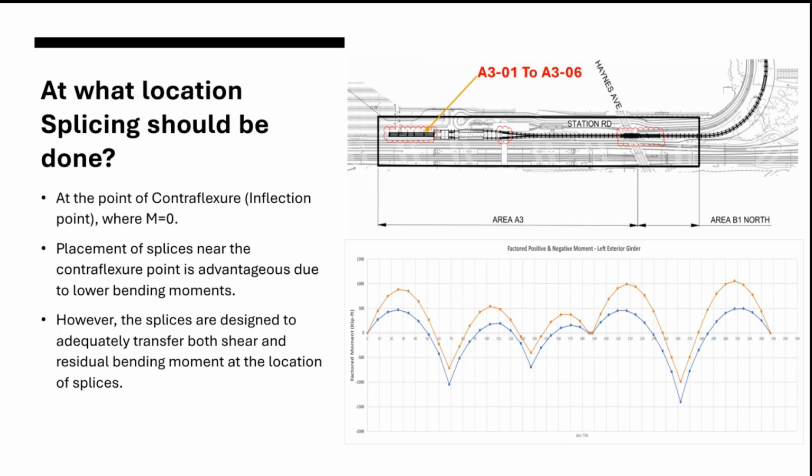If it's a rolled section, it gets tougher to do that big of a length because it would fail with its own dead weight if the piece is not picked up well. So for rolled sections, in practical application in general, we go around 100, 110, not more than that. For the plate girders, you go up to 140.